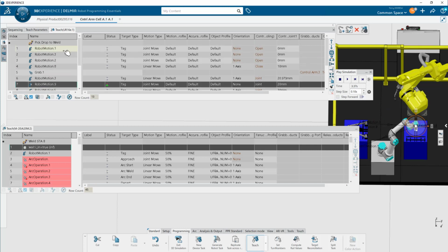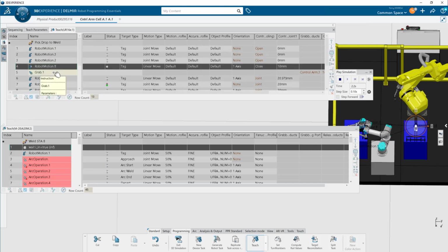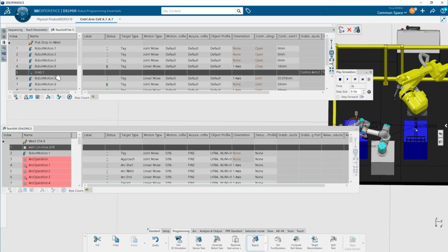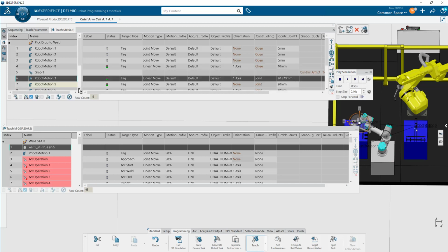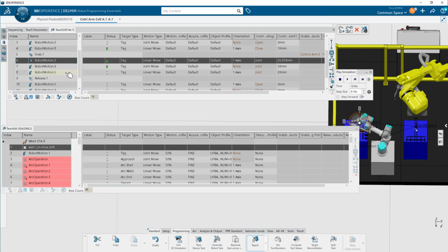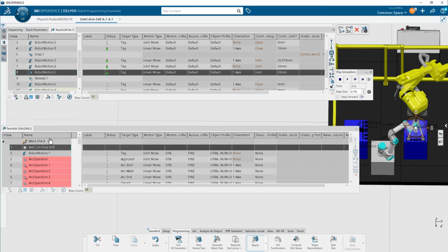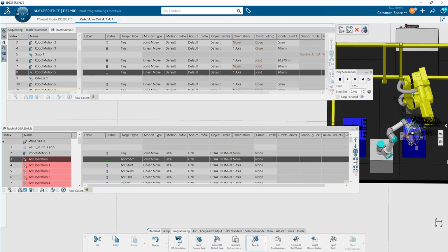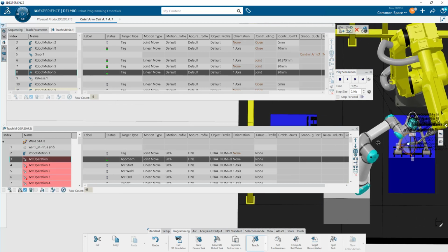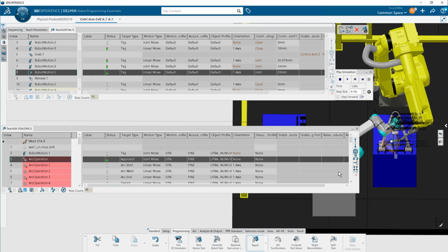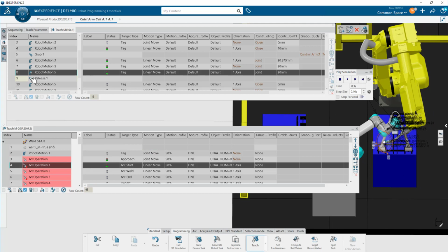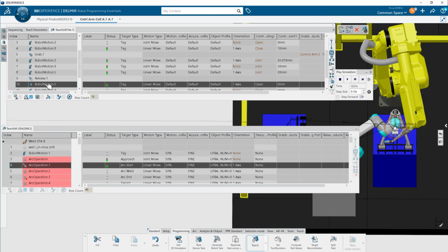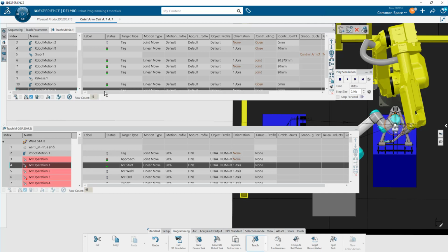And you can go back and forth from the universal to the FANUC and the FANUC to the universal. And this is a really slick way of being able to sequence these robots visually so you can visually see where you need to input your wait statements or input turning on an output or turning off an output and things like that. So it's a very sophisticated methodology of sequencing a work cell. If you have a lot of devices and you have a lot of robots, it's very sophisticated, and you can create very, very complex programs using everything that we've covered so far.